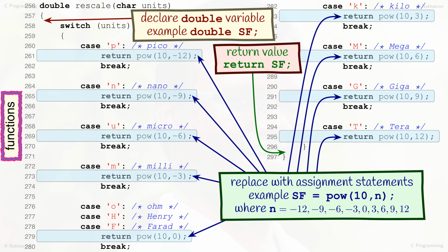It might look like 8 bytes is a very small amount of RAM, and the data communication between the microprocessor and the RAM to access the double variable value is going to happen only a few times. But we should always keep in mind that a function can be called many times due to large computation, and in case of processing huge data and continuous monitoring of signals and systems, it can lead to a big amount of memory and processing time. So, it is always better to develop optimized code with respect to cost functions like memory resource, processing time, and data communication speed and bandwidth.